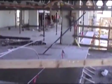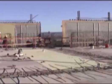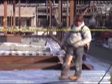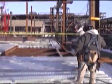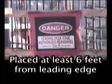Another system of protection is the warning line system, which is used mostly on roofs and is designed to warn a worker that they are approaching an unprotected roof side or edge. The warning line designates an area where roofing work may take place without the use of other fall protection systems. The barrier is a warning line consisting of rope, wire, or chains placed at least 6 feet from the leading edge and flagged at 6-foot intervals with high visibility material.